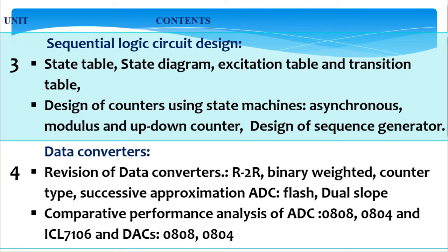The contents are revision of data converters such as R2R digital to analog converter circuit, then binary weighted data converters, then ADCs such as counter type ADC, successive approximation ADC, flash ADC, and dual slope ADC.